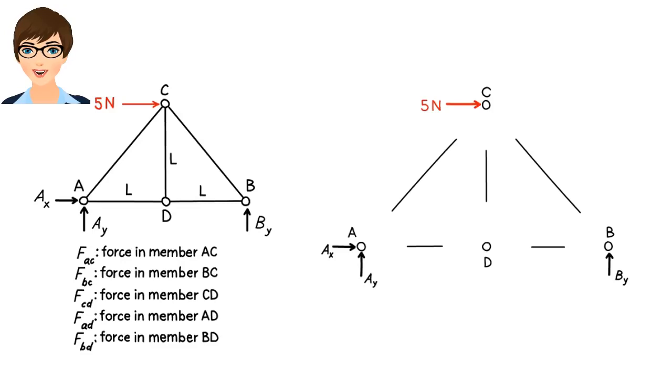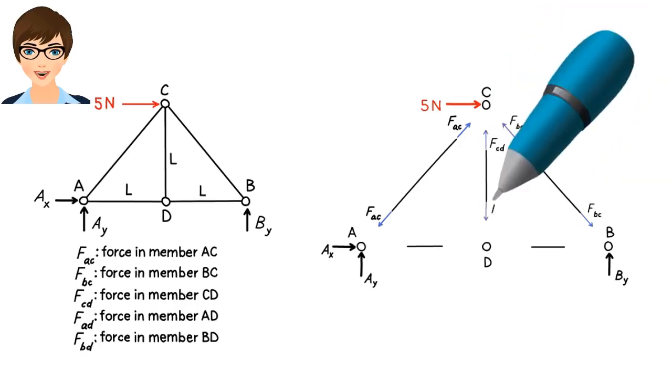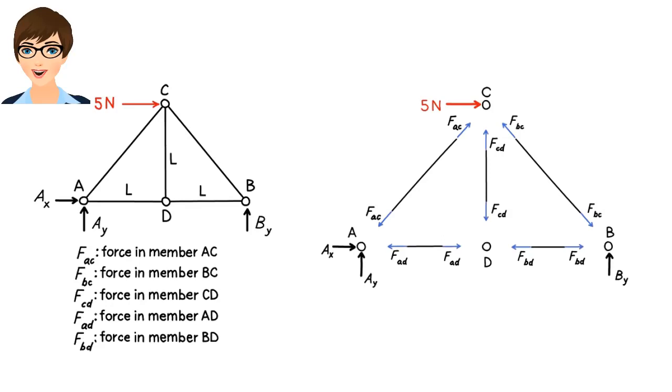Since I want to draw the free body diagram for the segment, I need to assume a direction for the force. I'm going to assume the member carries a tensile force. So, the free body diagram for the segment looks like this. The only force present in this diagram is the unknown tensile force, which we have labeled FAC. I am going to draw the free body diagram for the other members in a similar manner, where each member is assumed to carry an unknown tensile force.